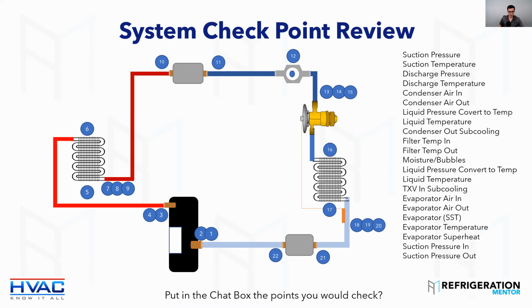So you use a suction dryer and then take it out afterwards. Now, if you talk about a refrigeration application like a supermarket rack, they have suction filter dryers on them, and there's different ideas on it. Some people say you got to leave the filter dryer in. Some people say you got to take it out. For me, I would always have a filter dryer in. The real purpose of that is to collect any copper, any shavings, so it'll protect the windings of that compressor. But that's another thing that needs to be checked.